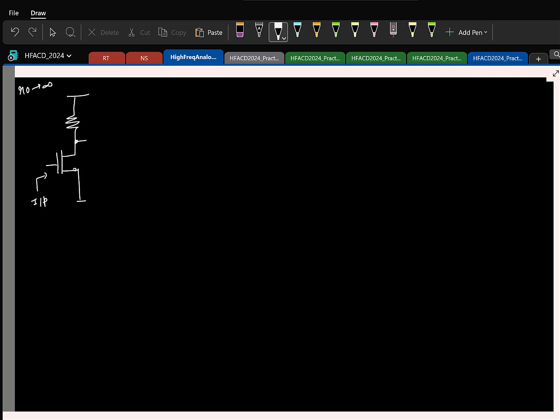So again, to find the voltage, let me draw this here. What we are essentially trying to do is model this noise here using this fellow. Everything here is noiseless, and the noise is coming due to an effective current and a voltage. And you guys know, since the input impedance is infinity, only the noise voltage is enough for this guy.